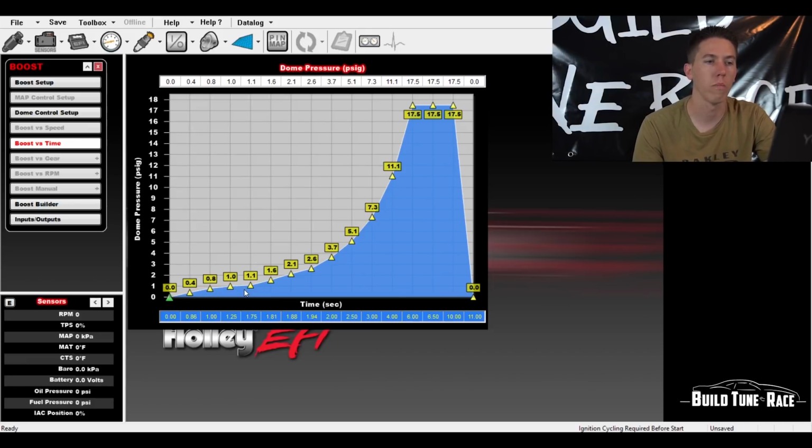to try to keep the tire hooked. But then I was running into where it would still make more boost on the line, so I've got to come up with a way to where the car will make maybe 1 pound of boost on the line and then ramp from there, because I know it'll hook the tire there. When it makes 3, it wants to spin the tire.